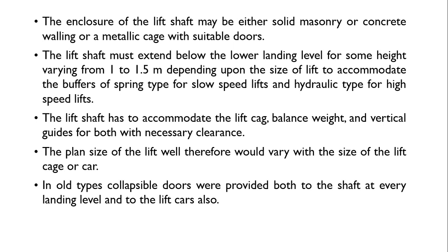So here the lift shaft is provided for the lift. This lift shaft should accommodate the lift cage, the balance weight to balance the cage weight, and vertical guides and ropes, with the necessary clearance. The plan size of the lift therefore would vary with the size of the lift cage or car.